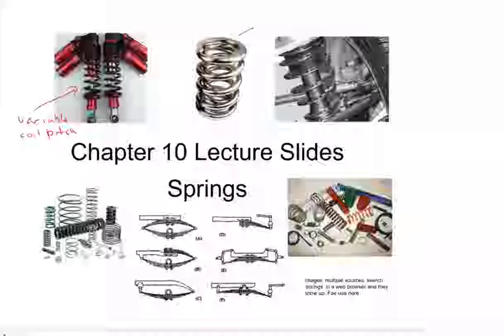This is a two springs, one packed inside the other. This will give you a heavier stiffness without any increase in the package size. Here, instead of variable pitch, we have variable coil diameter. Usually this is done to give you a different stiffness as springs collapse.